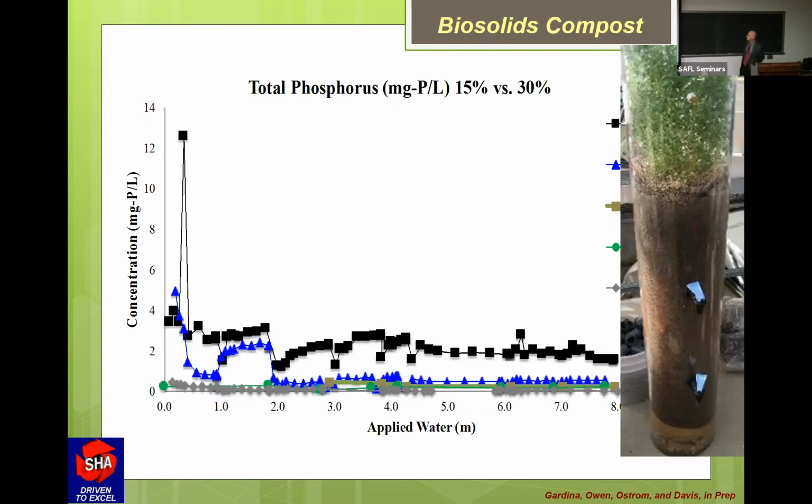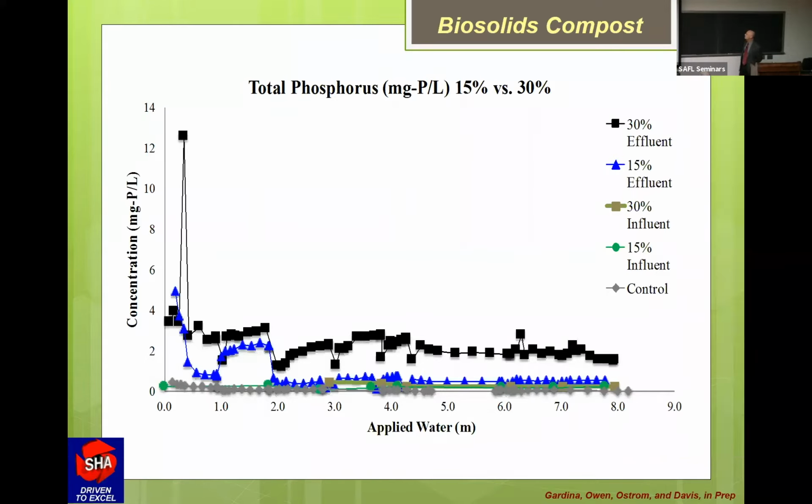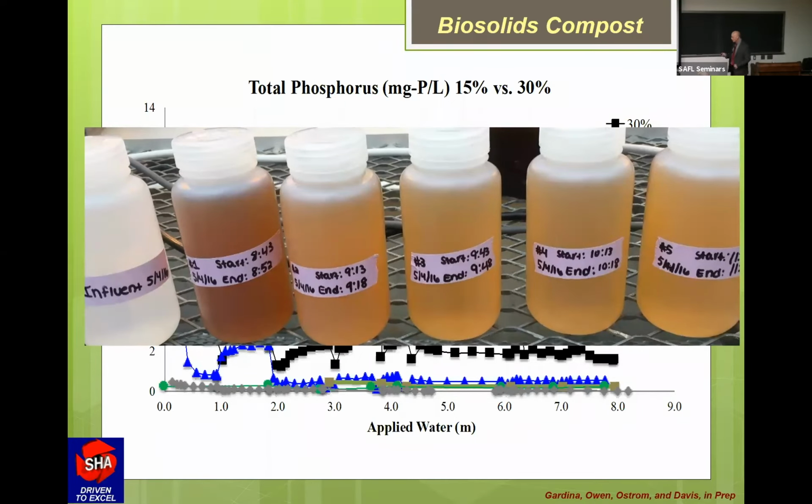And we did a lot of studies with different types of compost. And the compost is going to leach nitrogen and phosphorus. Biosolids was over the roof with concentrations of phosphorus and nitrogen. Some of the other types of compost weren't so bad. Visually, we can even see that. We were only putting in dissolved phosphorus, so our input looked like this, and what we were getting as output was from here. So anytime you're dealing with compost in these stormwater control measures, you have to be aware of the leaching of nitrogen and phosphorus. And when we go back to my original cell, why we were leaching phosphorus is we did have some leaf compost in that original system that we put in 15 years ago.